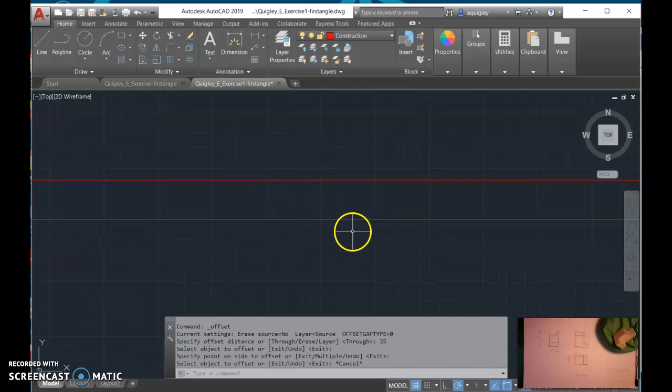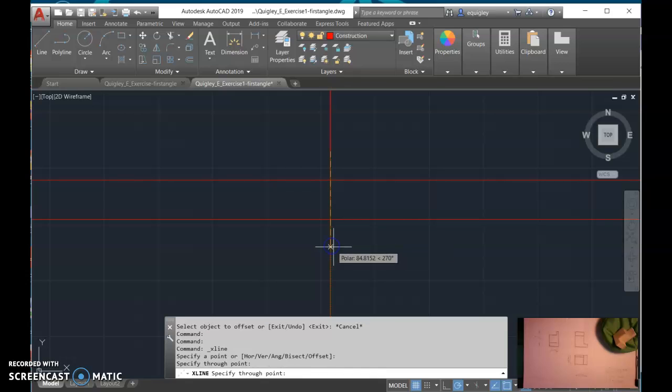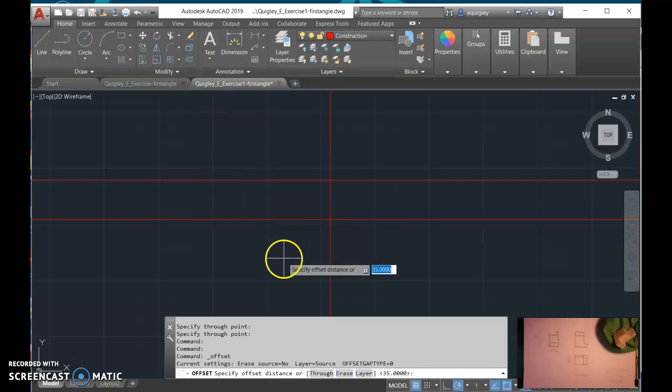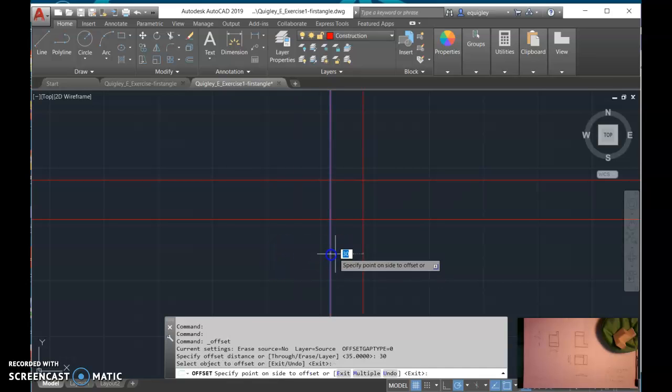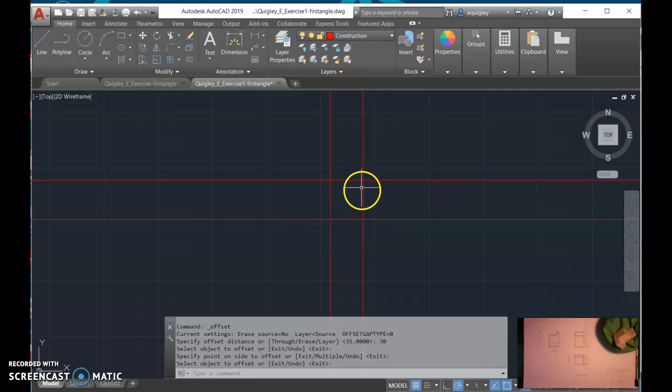So the width of the object, we need a vertical construction line to share the width of the object information. So construction line again, and just draw a vertical construction line. Press enter, and the width of the object is given to us as 30, so we'll use offset and a distance of 30. Here goes. Okay. So our front view or elevation can be landed in here.